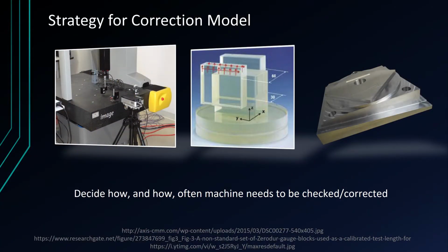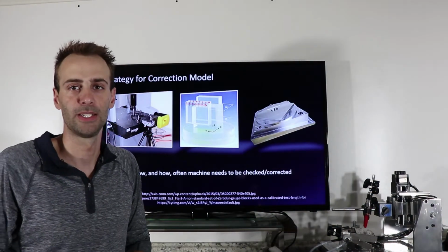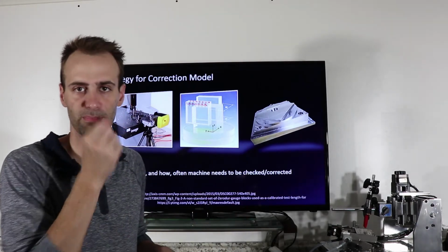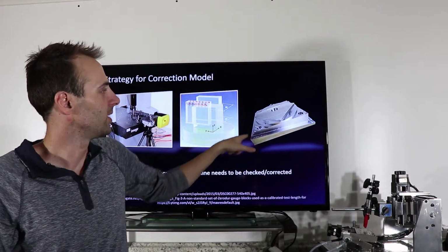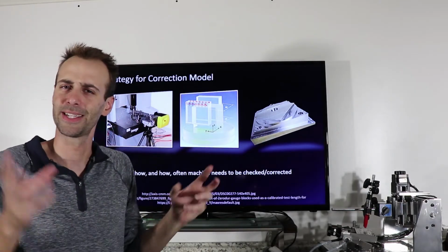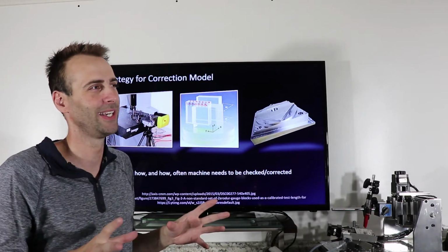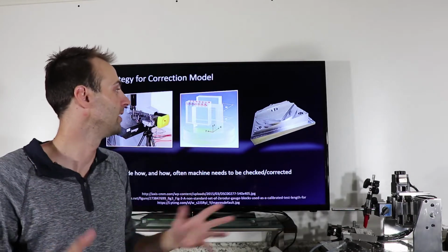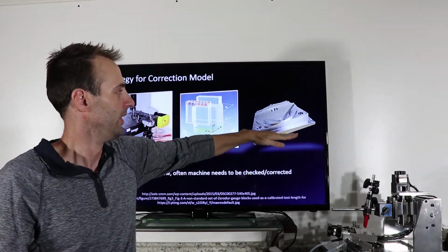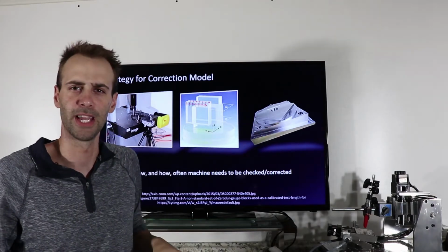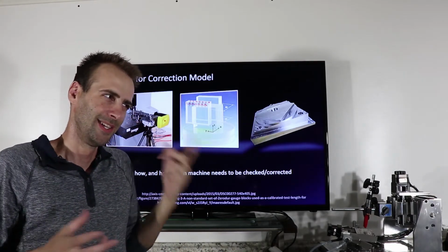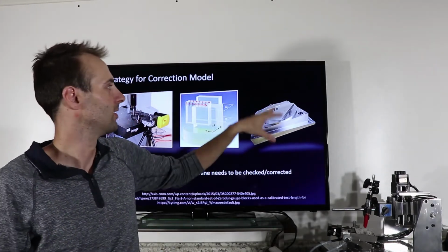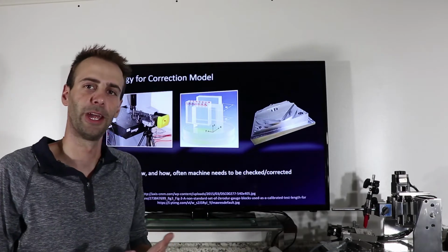Okay. So this example here is in the aerospace industry. I think NAS 979. If it's wrong, I'll put it in the words here. But this is a 5-axis part, and I'm pretty sure that the standard says it needs to be hand coded, but that's insane because this is a 5-axis part. If you notice, this ramp around the part is actually on a tilted plane. So I don't know too many people that are going to be hand coding 5-axis parts, but nonetheless, there are standardized things, and they call this the circle, diamond, square test.